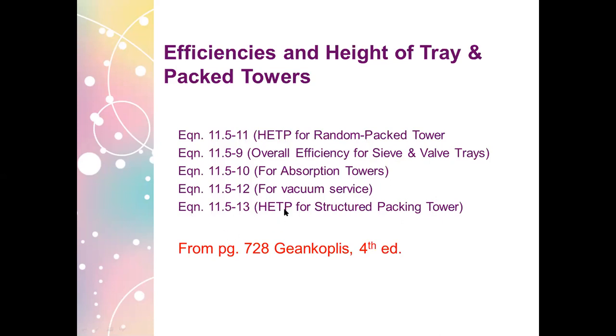So I did not write it here. You just have to locate it in Coulson, please, in this page. By the way, this is the Philippine edition, the one that is colored black. So you will have these equations there. So take note that we have a different formula for structured packing and for random packings. And this one accounts for the overall efficiency for a sieve or valve tray. And this one is for a vacuum service.